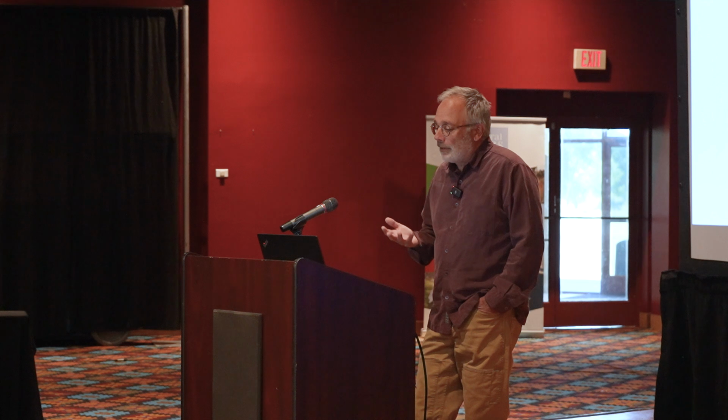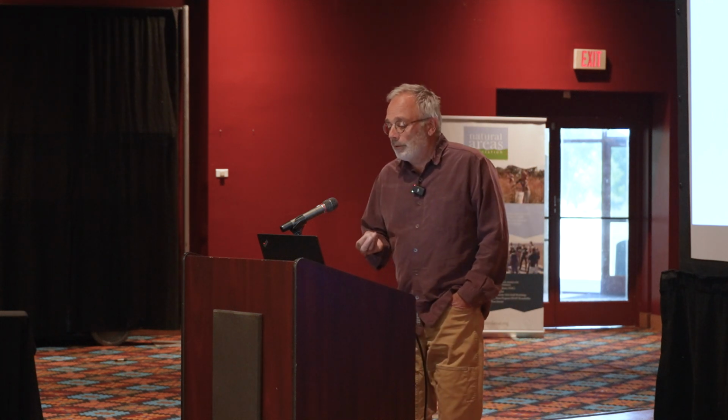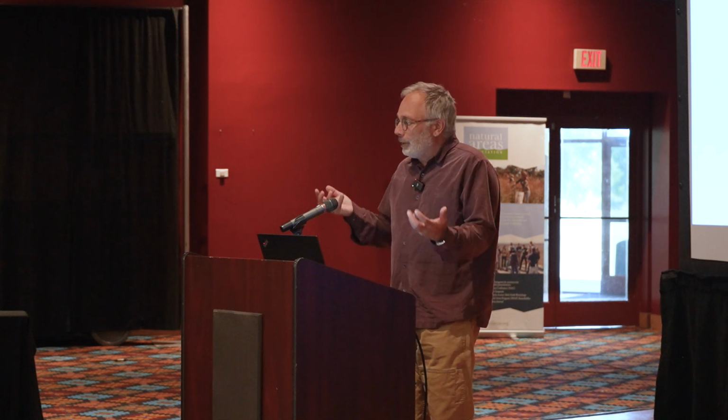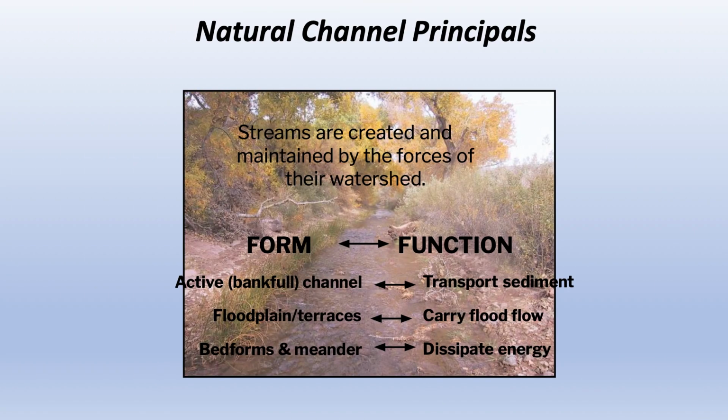But the key to this is these natural channel design principles. And the first one, the most important one, is that your form is roughly equivalent to the function of your channel. If you understand the channel shapes and you understand the valleys that surround them, you can rapidly measure those and estimate what the function of that's going to be, as in wide, shallow channels are very poor at sediment transport relative to narrow and deep channels because of the shear stress distribution in those.